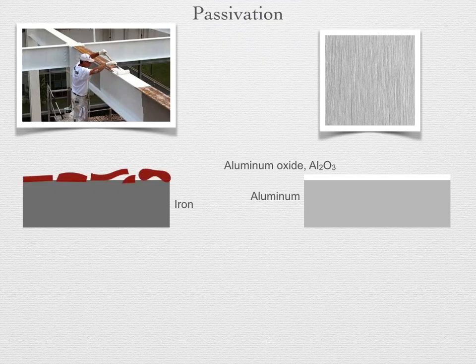By contrast, a freshly exposed layer of iron also quickly forms a layer of iron oxide, Fe2O3. This material, however, is not well suited to remain bound to the underlying iron lattice. The atomic spacings are too dissimilar. Instead, as it grows, it cracks and flakes off, revealing new iron surfaces on which corrosion begins again. Iron rusts destructively because its oxide does not form a passivating layer. Now, this is true of high-strength carbon steel alloys, which have about 1% carbon.